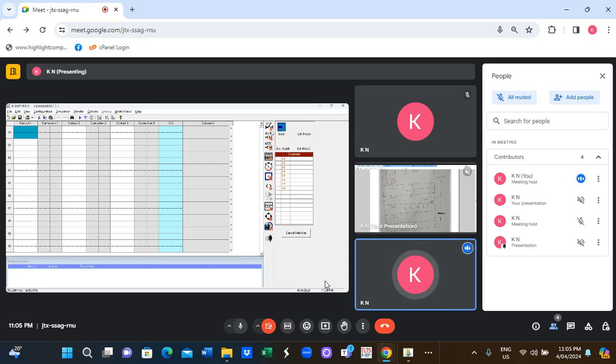So there is input, output, auxiliary contact, timer and counter. Now I am only interested in inserting the input, normally open or normally closed, and the output coil. I want to put the light and also the auxiliary contact for the contactor coil. So regarding input and output, I will put normally closed and normally open buttons, and for output I will put the lamp, and for auxiliary I will put the contactor coil. Those things I will do.